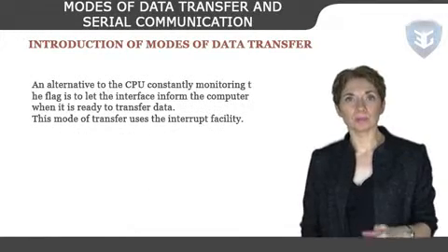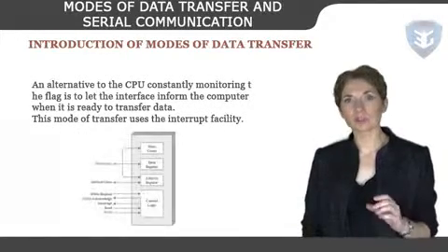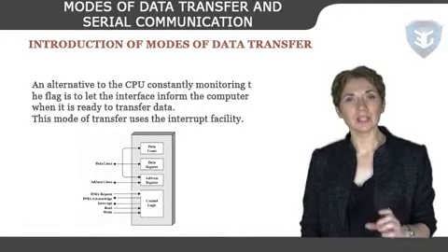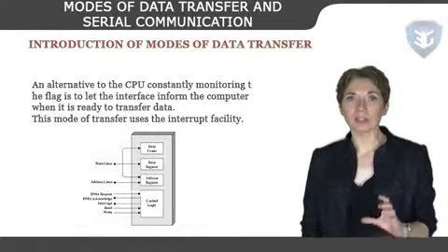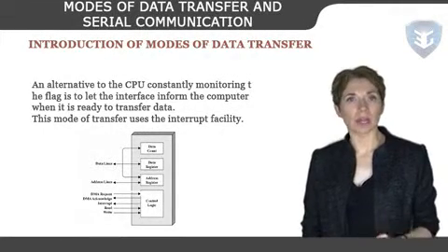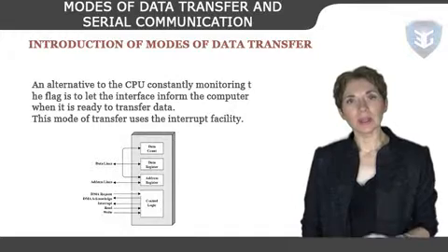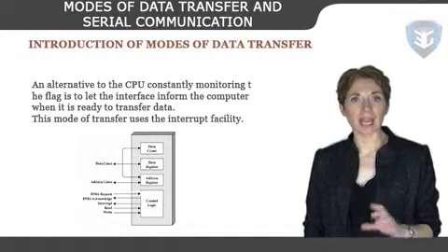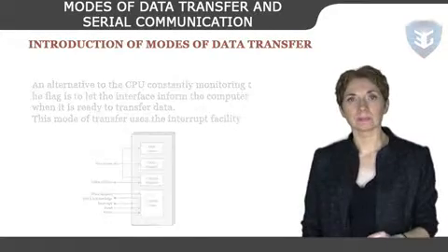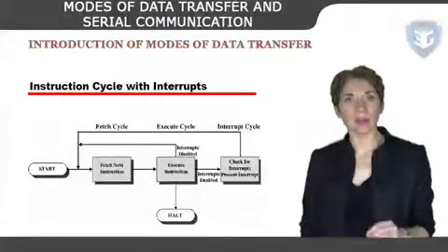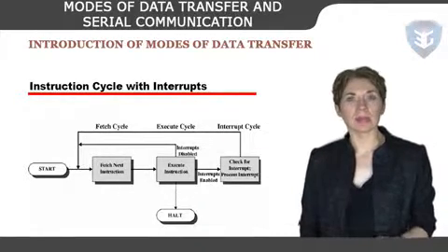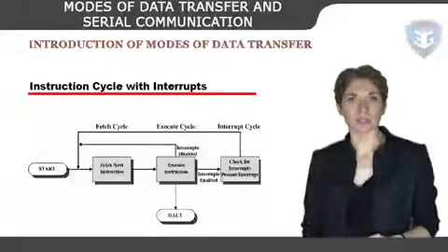The CPU responds to the interrupt signal by storing the return address from the program counter into a memory stack, and then control branches to a service routine that processes the required I/O transfer. The way that the processor chooses the branch address of the service routine varies from one unit to another. In principle, there are two methods for accomplishing this. One is called vectored interrupt, and the other non-vectored interrupt.